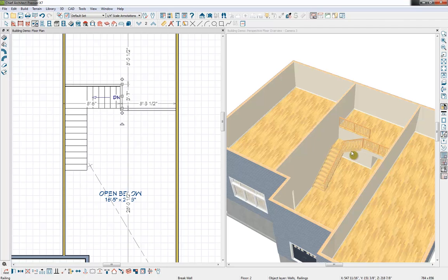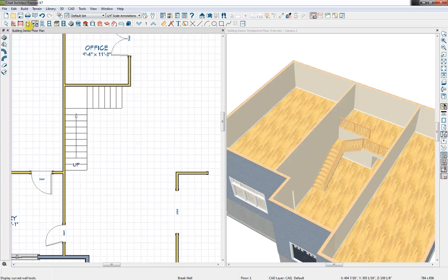And I'm going to draw in some walls underneath our stairs. So I'll go right back to our first floor to do that. Select our interior wall, and I'm just going to click and drag that wall right underneath our staircase. So with our program, it will just automatically clip those walls. So we can easily create a storage area, or if we're going to do some more stairs down to our basement, kind of defines that for us as well.